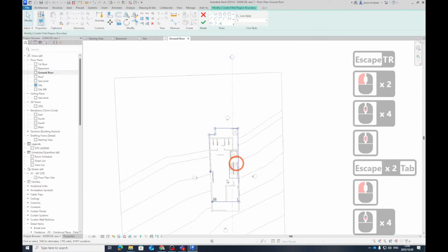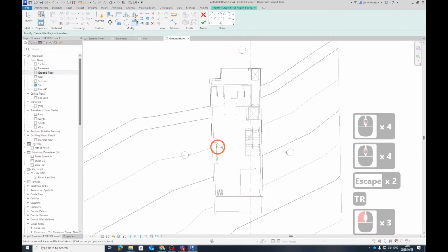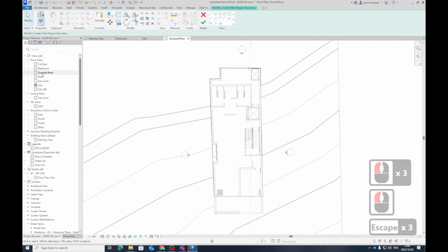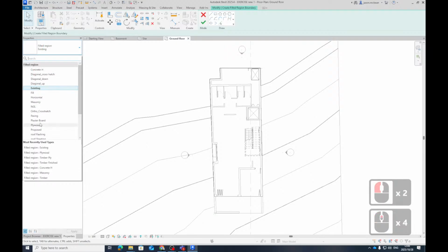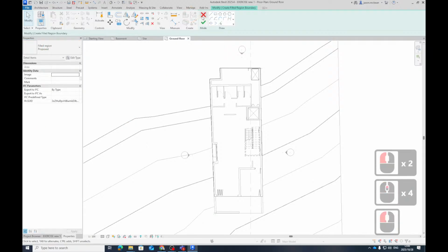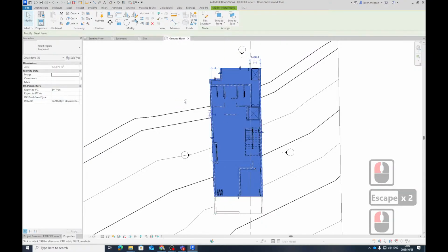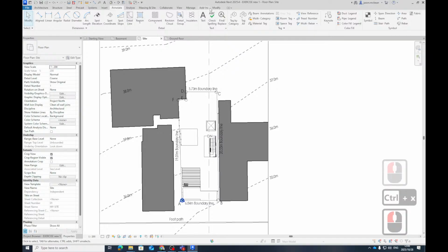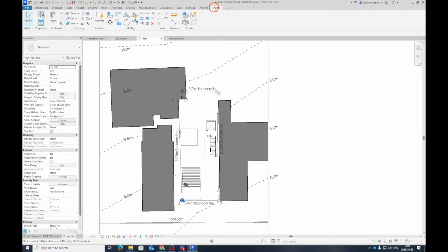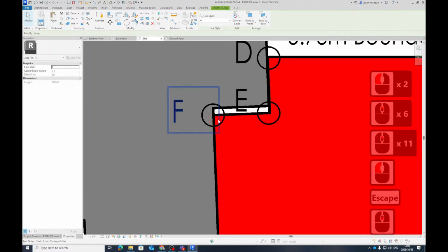Now press tab. Here's one last little glitch, so trim that. So this will be proposed. Now this doesn't belong here, so click once, Control X, cutting it, going back here, paste. You're going to go to modify, paste, align to current view. Done. So there's your building now.